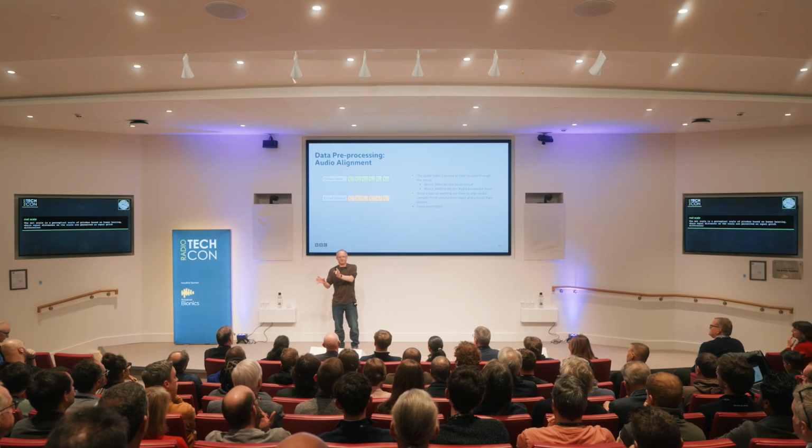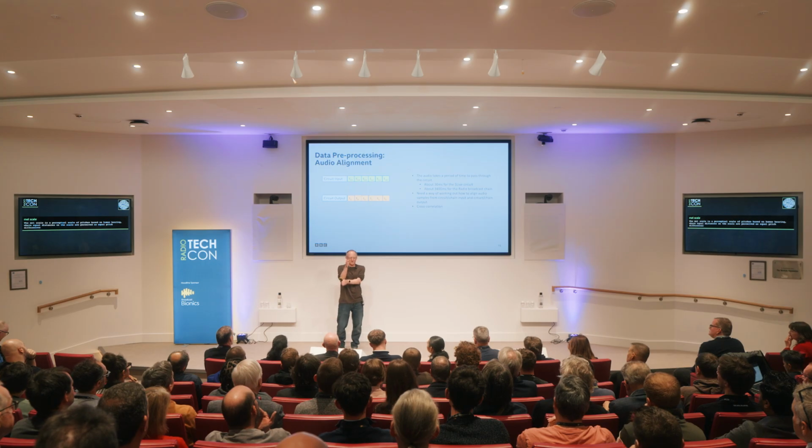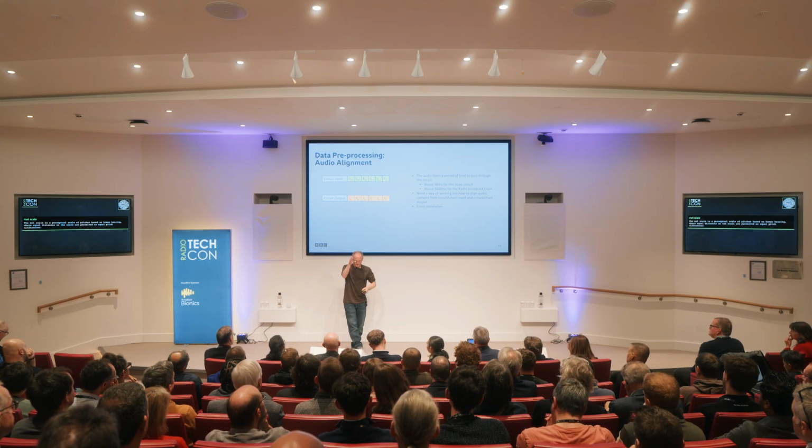What you really do is you take chunks of audio samples and you multiply your inputs and your outputs together, and you add them together. And then you shift it by a sample and you do the same, and you look at the value where it's highest, and that's where it's mostly aligned, which would obviously take ages.